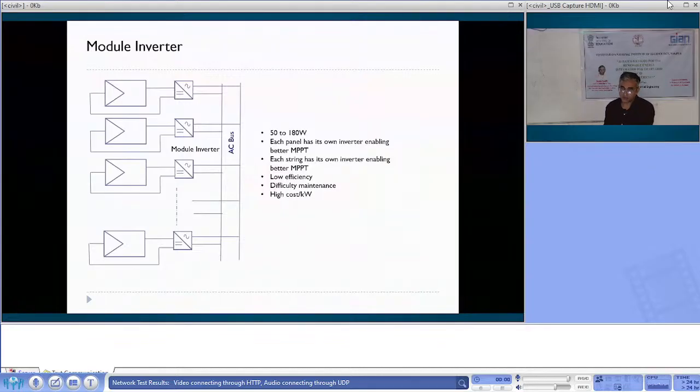But the radiation received by one cell may be different from the situation of the entire plant. Some panels do not get cleaned, some birds are sitting on the panel, some shading of a pole or shadow is coming but not falling on the reference cell. So one cell is not a correct representation of the complete power plant.